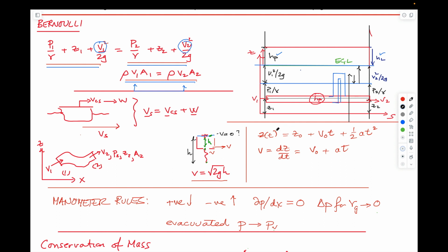We talked about moving coordinate systems. That's pretty straightforward in that if we look at squirting water out of a boat at some velocity w, and the boat is moving at a control surface velocity of VCS, then the sum of those 2 is what a static observer sees. And so the sum of those 2 vectors gives you the vector for the static observer: the velocity of the control surface, and the velocity of water coming out of the boat relative to someone standing physically here on the boat.